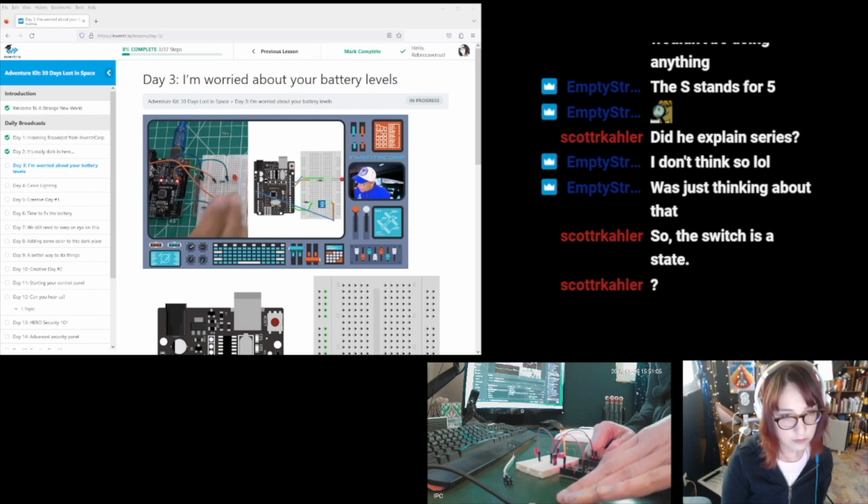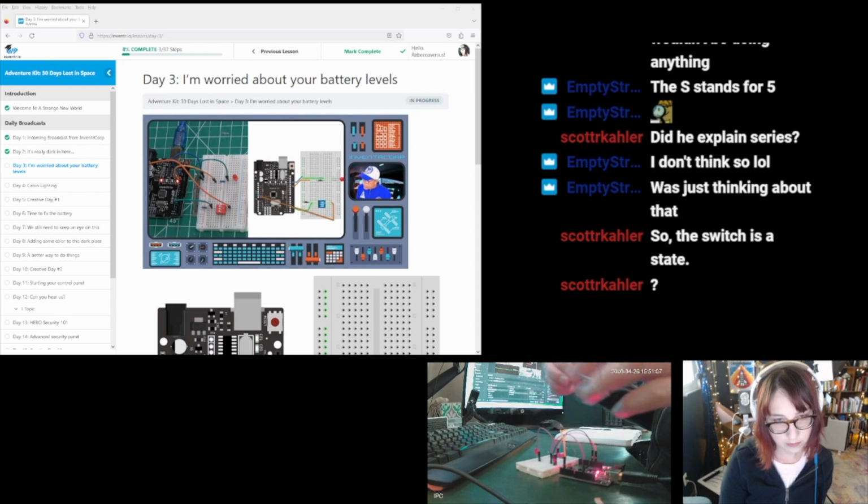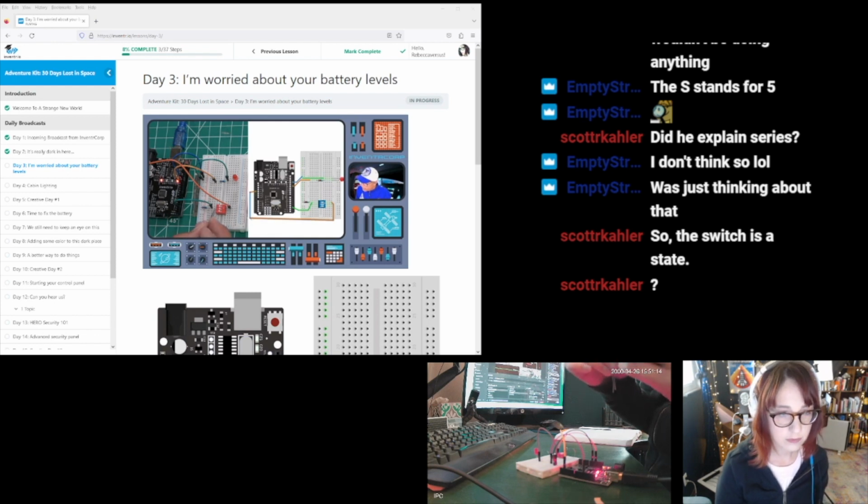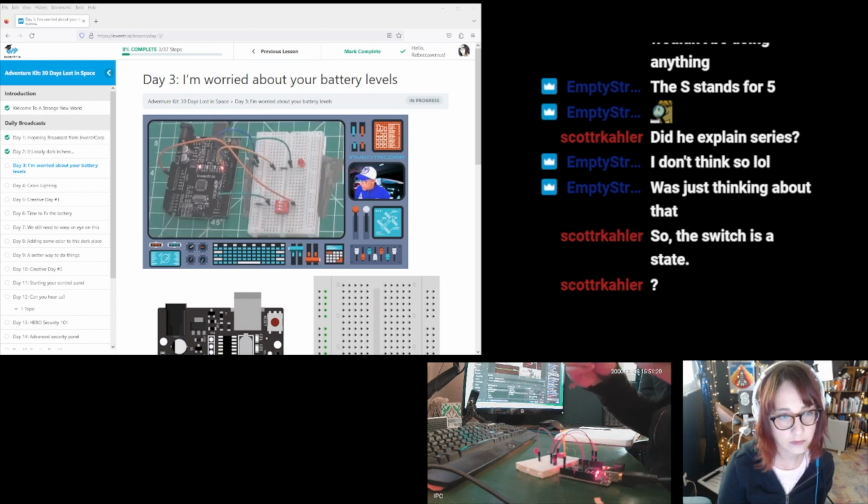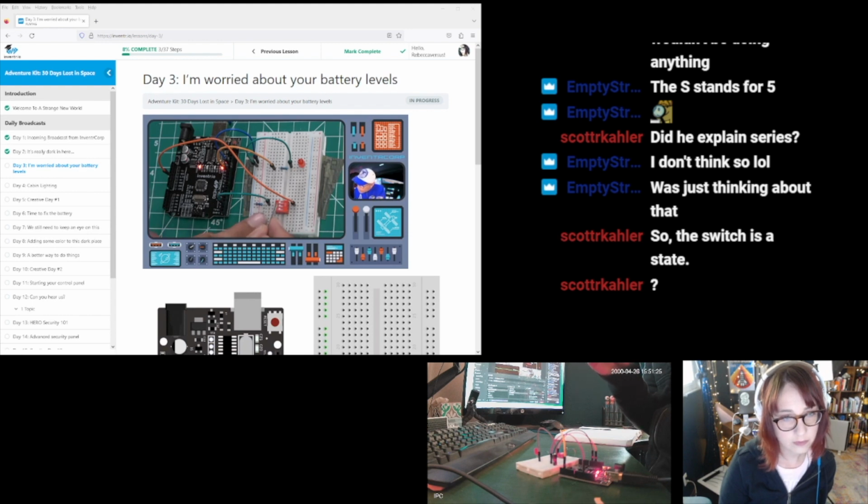Now, with the switch in the off position, that's not going anywhere. There's no completed circuit. And the left-hand side of row 23 is still at an indeterminate voltage level. On the other hand, if I were to switch this to on, the current can now flow through the switch, through this second resistor and down to ground.